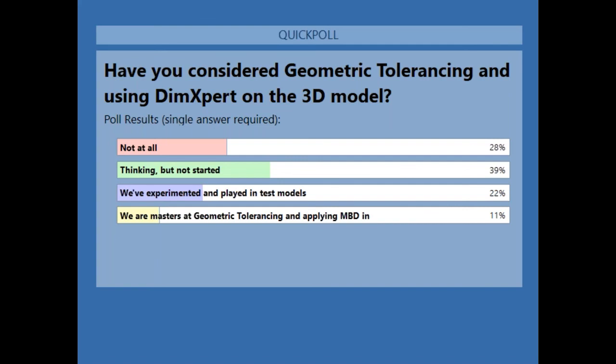In our manual or semi-automatic systems, you could use a probe with that part, but for fully automated systems on the shop floor, you would not. Depending on the size of the feature and how deep it is in terms of accessibility, you may not be able to measure it. But you can use either the scanner or the probe in those situations.